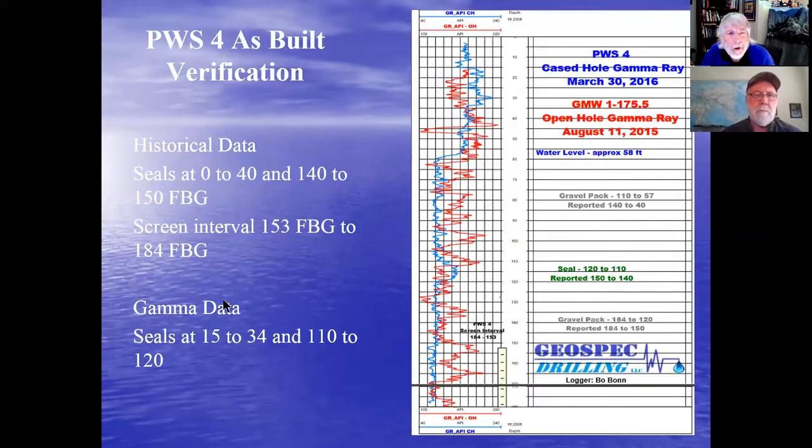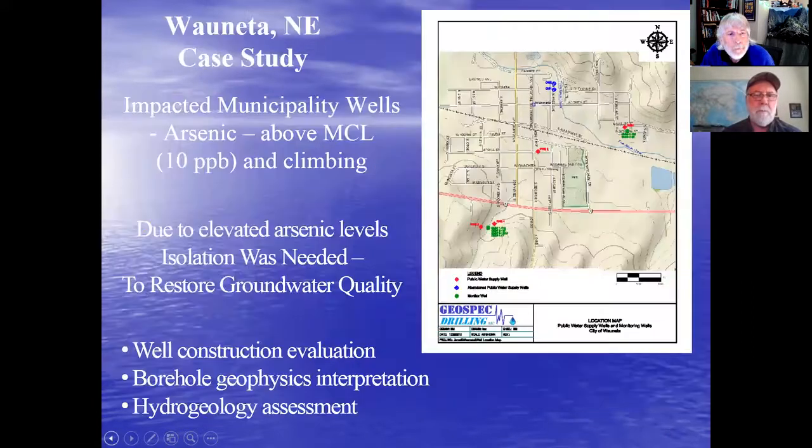And part of that effort, we would evaluate all the existing wells, all the municipality wells, and there are 4 out there at the site. We're going to look at the driller logs of those holes and also construction detail. We're going to run test holes and then run borehole geophysical interpretation, then provide a total hydrogeologic assessment of the area.